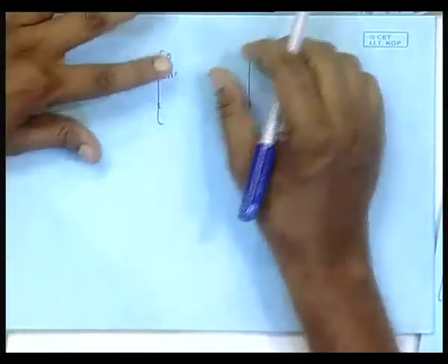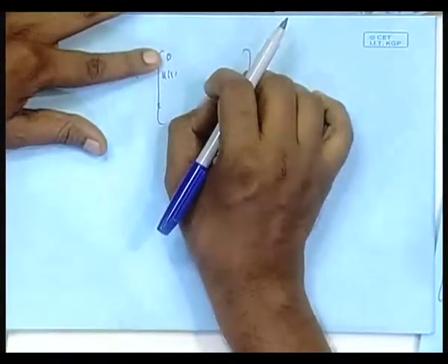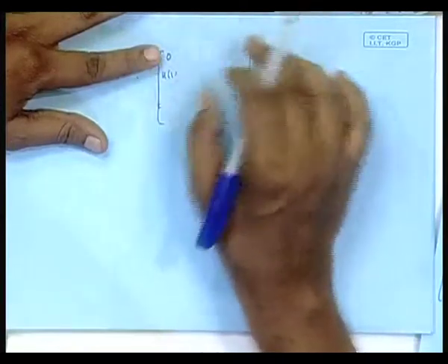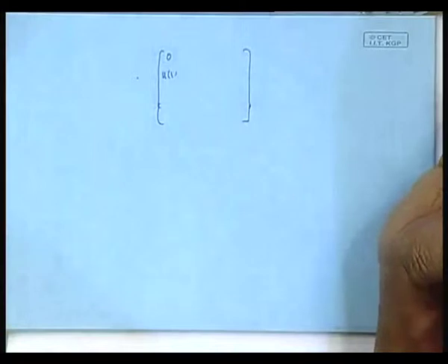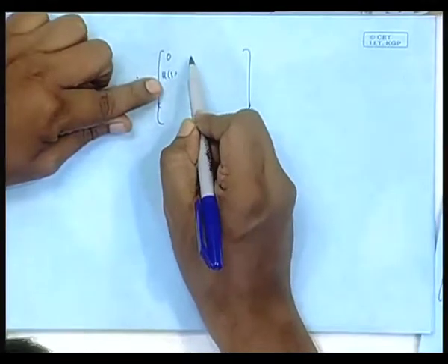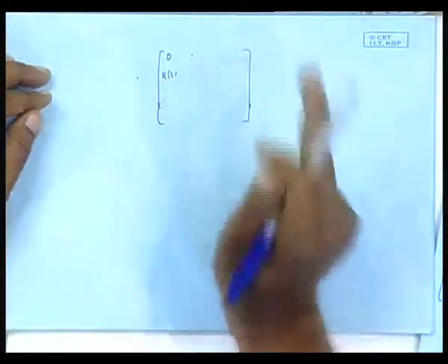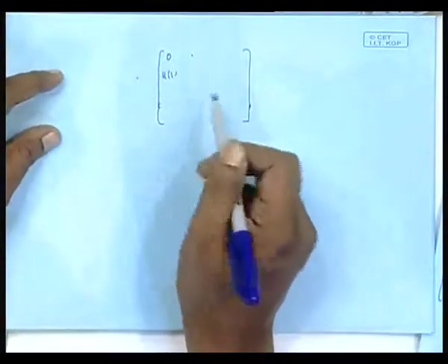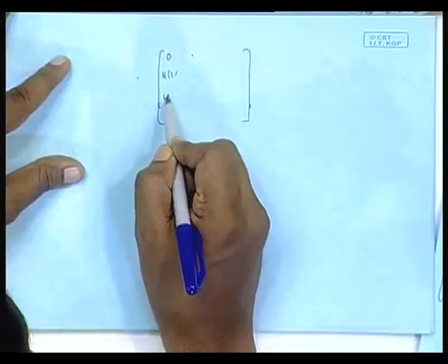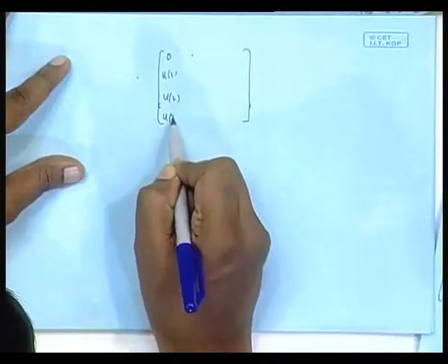Pre-windowed means whatever will be the first column, Z inverse of that will be the second, Z inverse 2 of that will be the third, and like that. Likewise, as we did in the recursive least square lattice. And 1 is my starting index, so 0 will be there on top always. Unlike there, here my starting index is n equal to 1.